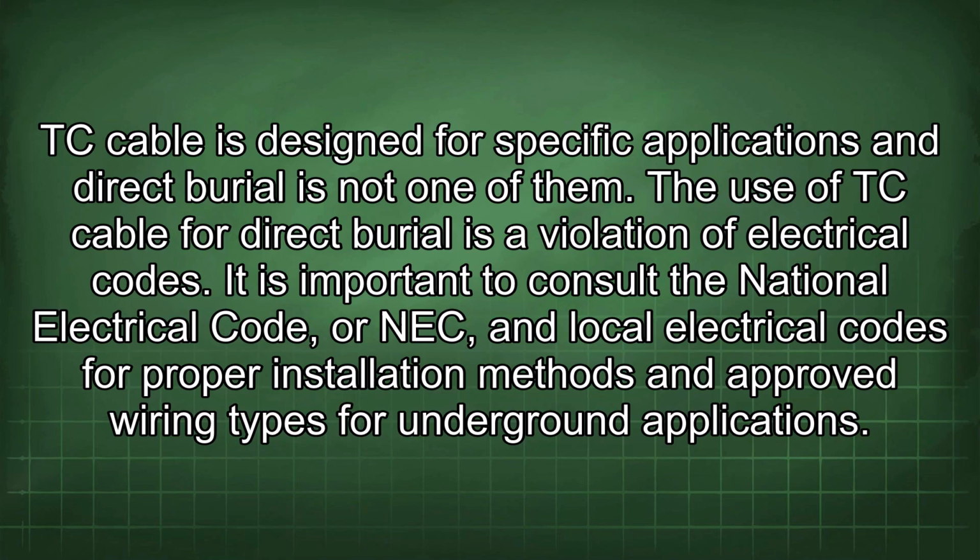TC cable is designed for specific applications, and direct burial is not one of them. The use of TC cable for direct burial is a violation of electrical codes. It is important to consult the National Electrical Code, or NEC, and local electrical codes for proper installation methods and approved wiring types for underground applications.